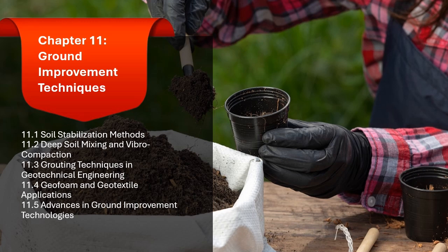Thermal treatment of expansive soils. Heating expansive soils can reduce their swelling potential and improve their stability, offering a promising solution for foundations in clayey soils prone to volume changes. Thermally assisted ground improvement. This technique is combined with other methods like grouting or compaction to accelerate soil stabilization, particularly in challenging conditions where conventional techniques may be inefficient.